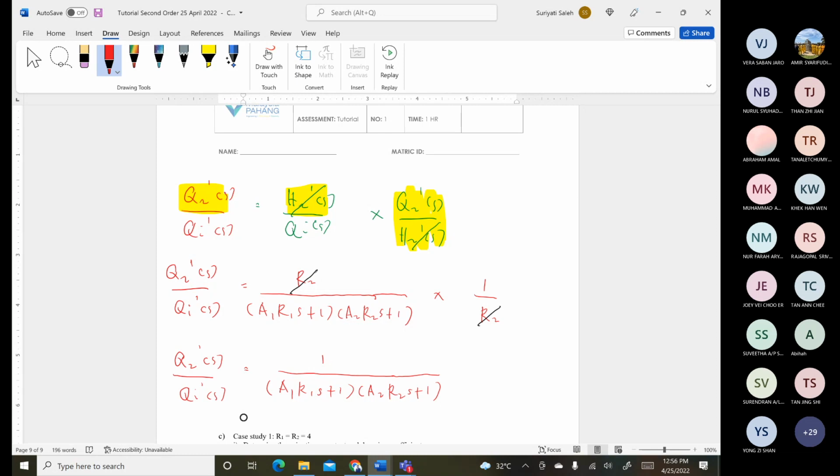So in this case, we do it one by one. And when we want to connect the tanks, we use the valve as our connector. This valve relationship connects the transfer function from the previous tank and the subsequent tank. So when we multiply it all together, it can connect the height or the outlet flow rate with the inlet flow rate.